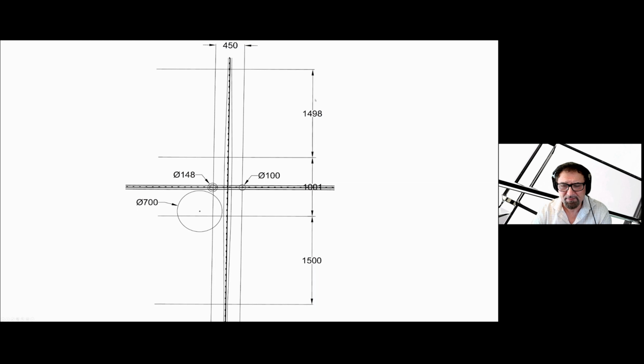I also have the taper length about 1,500 feet, and then about 1,000 feet in the middle to accommodate the grading, side grading, and also the bridge area in the middle. Then we're going to design 4 connected alignments. Using connected alignments, we'll design 4 curb returns, or if you like, on and off ramps that are direct access to the intersecting highways.